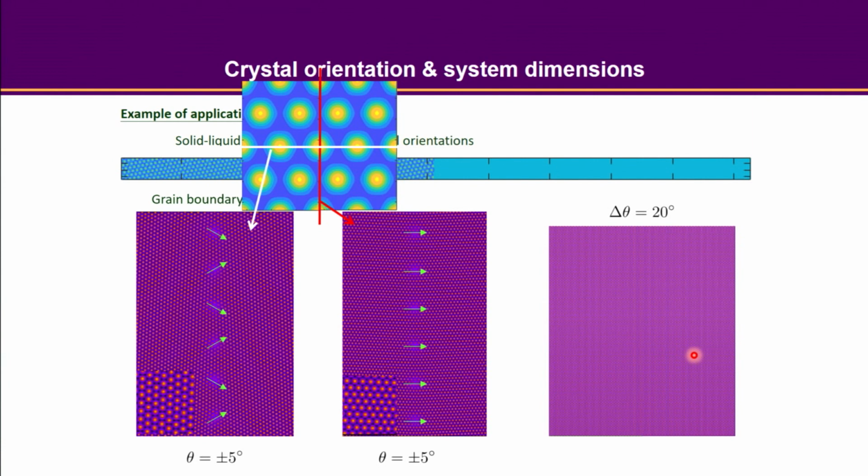Here you are seeing a very nice curvature-driven motion come in. You can also try the system with a smaller misorientation, like 5 degrees. Then you are expecting the grain boundary structure to be something discrete, and the dynamics will be quite different. That's something we can already do with the system size properly set like we just discussed.